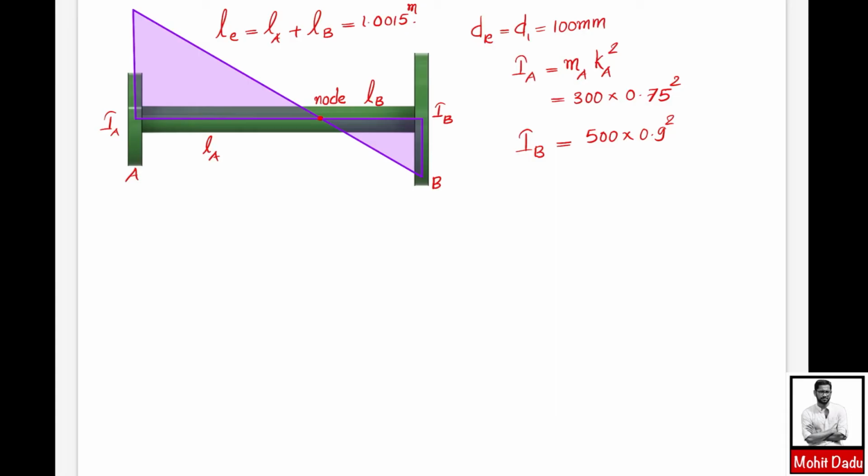So we have studied in the previous lectures for this two rotor system. You will be splitting this two rotor system into two single rotor systems based on this node point. Then the natural frequencies of those two parts will be the same, and from that concept you have derived a relation connecting this IA and length LA. That means the location of the node. That is, the product of LA and IA will be equal to the product of LB and IB. So here the unknowns are actually LA and LB. That is the position of the node within this equivalent shaft.